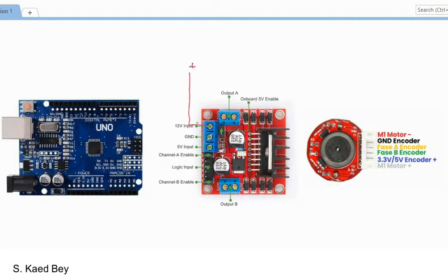this to a voltage, and that is the ground. That voltage is going to supply the motor. Now, for our purpose, we're going to supply this with 8 volts because we have a 2 volt drop across the H bridge. So if you supply 8 volts, you're going to get an output of 6 volts for the motor.